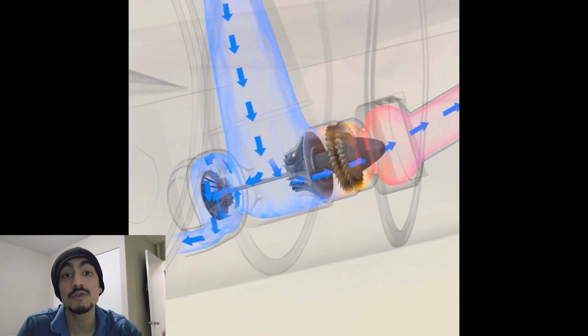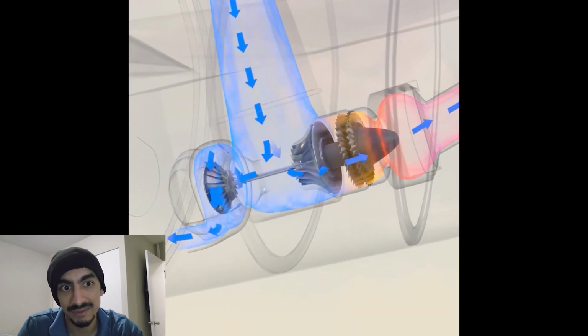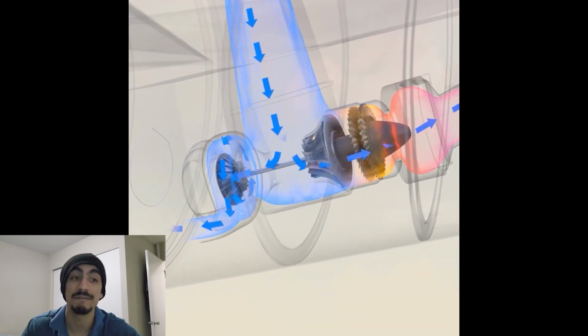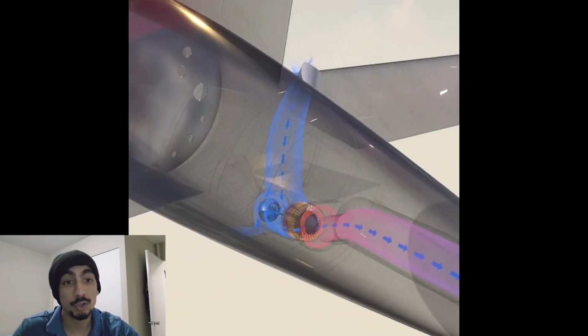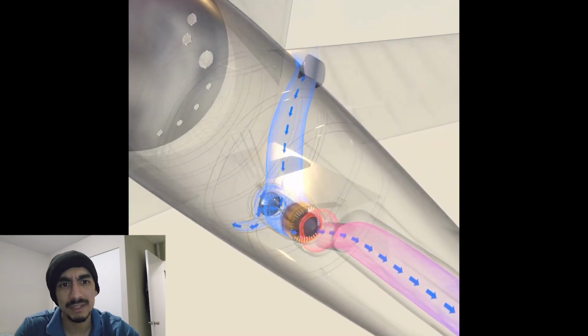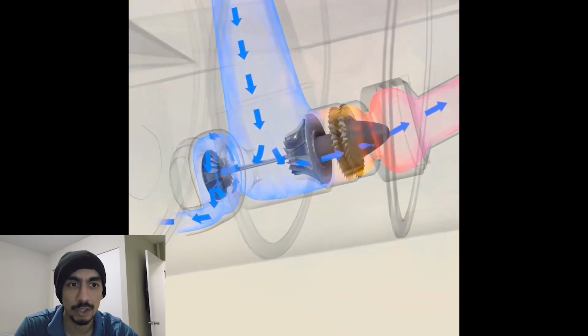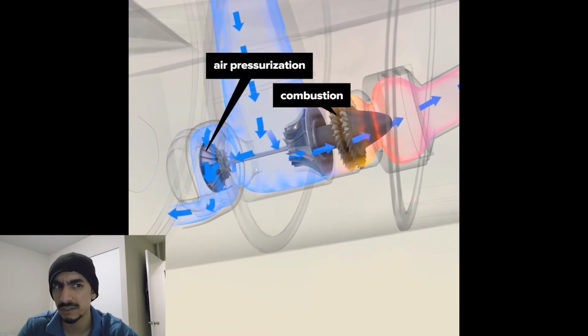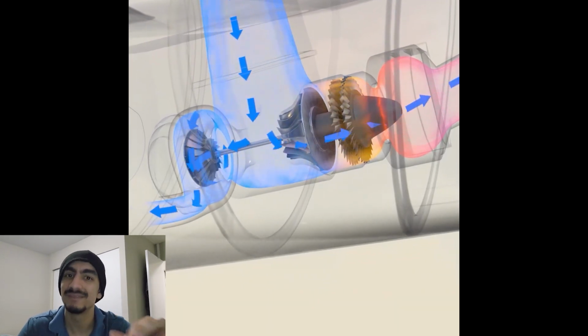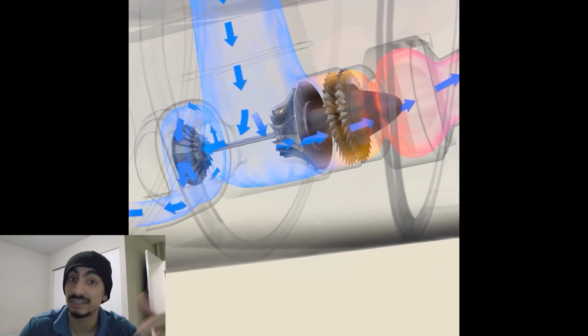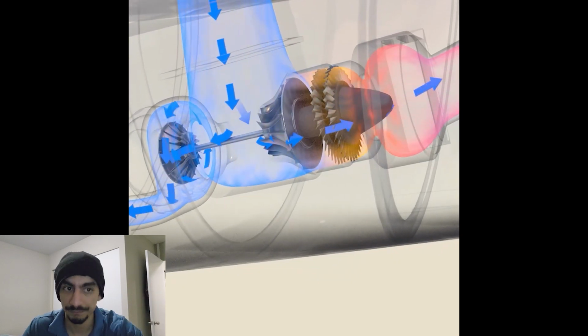So if you, for example, lose one engine, the APU can step in, and it can provide the electricity needed for navigation, for instrumentation, even for hydraulics. So it's like a small turbine. As I mentioned, it's located in the tail of the aircraft. It doesn't provide thrust to push the airplane forward, but it generates electricity. Sometimes it can even generate pneumatic air power.